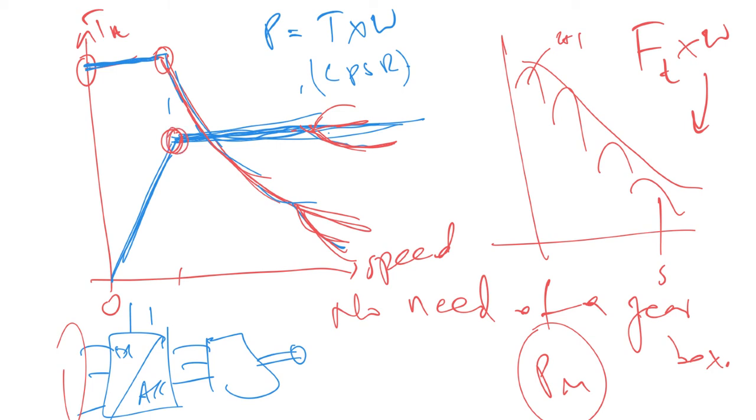That's the rating. That's how these machines are rated. When you say the power rating of this machine is this, they are talking about this point right there. And with a suitable drive, you will be able to retain that power for a certain duration of time. This region here is called the field weakening region, but that's a different concept altogether.